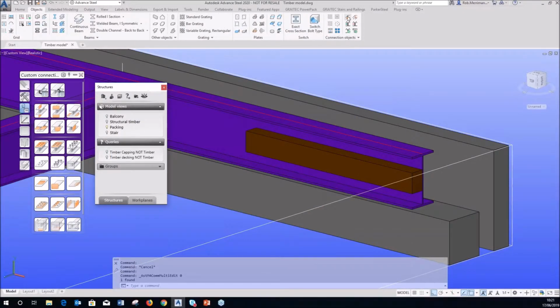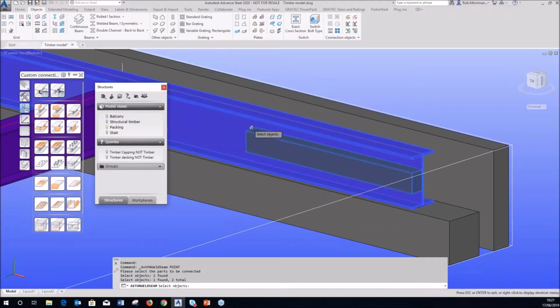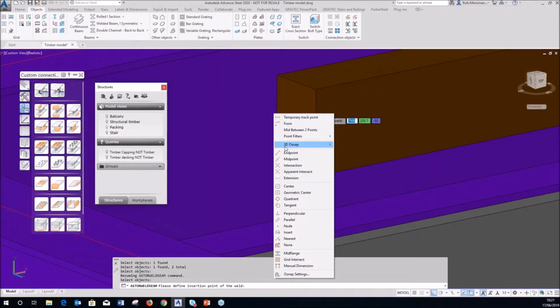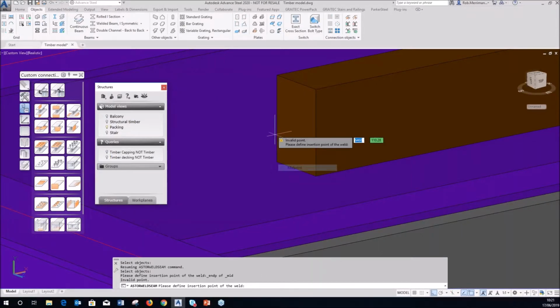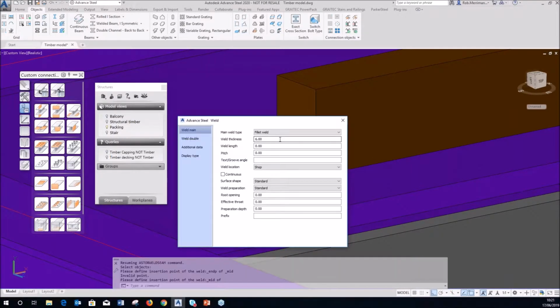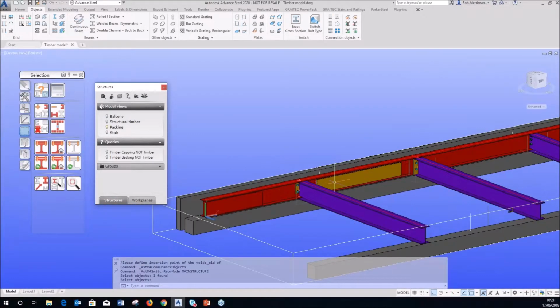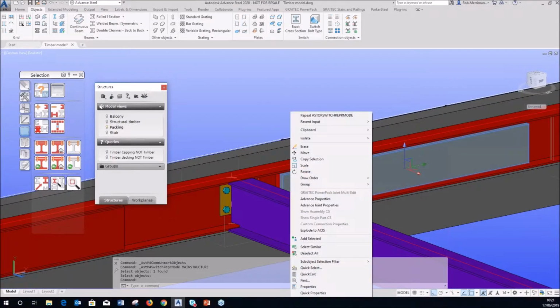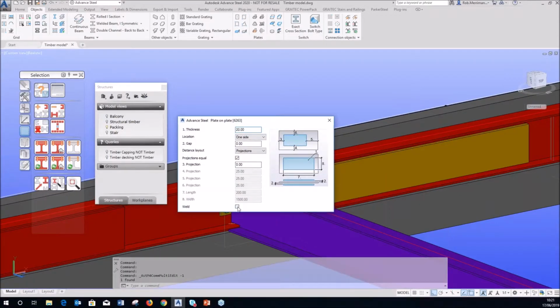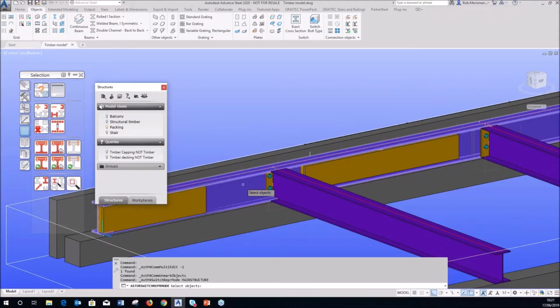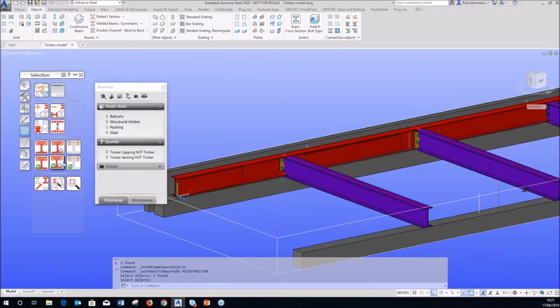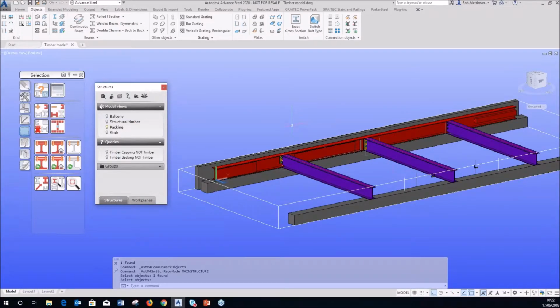But now, because I've modeled it as a beam section, the system thinks it's a steel beam. If I choose the right point, I can now weld these two together, and we can just double check. So I just need to create a weld between those two because they weren't all attached. So if I do show me what's attached in the workshop, I have covered all of this tab and checking things on my webinar for checking your Advanced Steel model. So they are now all attached in the workshop.